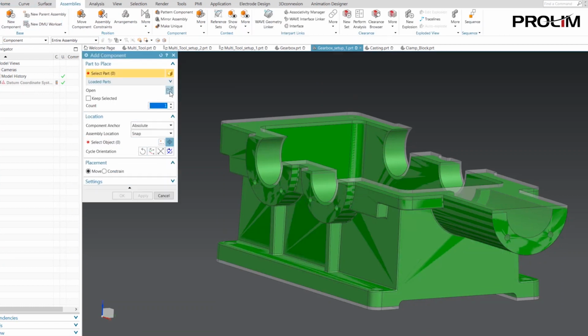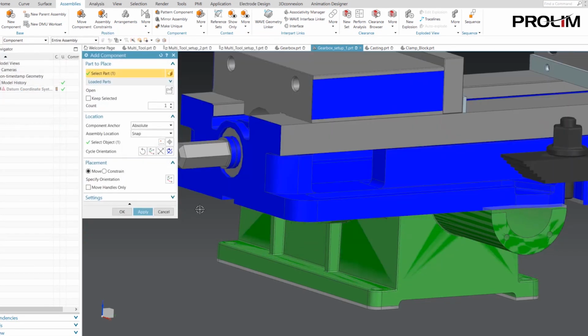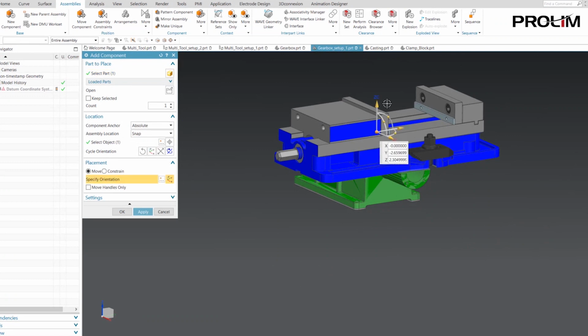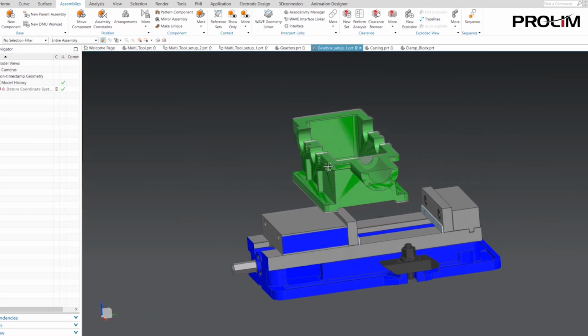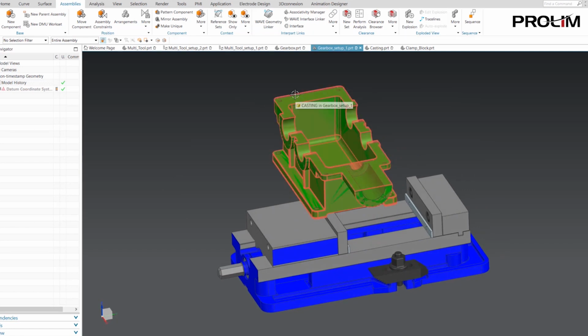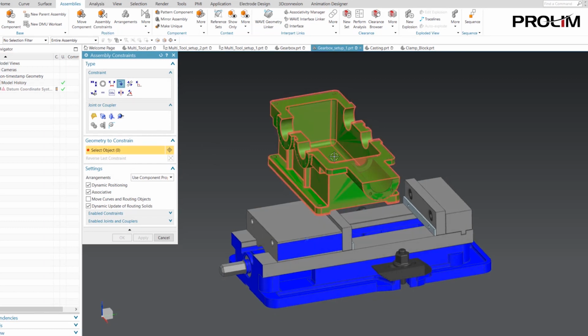other components such as a vise and constrain. Make our assembly constraints at this point using our geometry that we created. I always like to start with that fixed constraint. And this one we don't have to bond together because it was created using that associative linked copy.